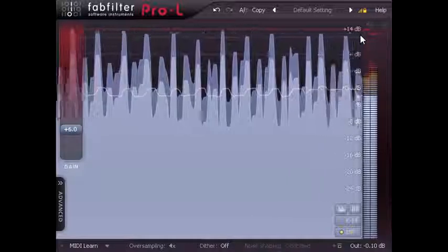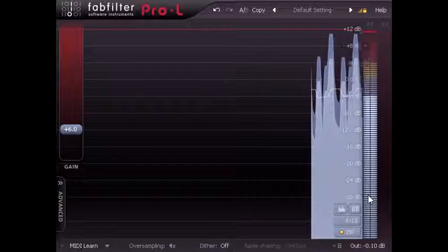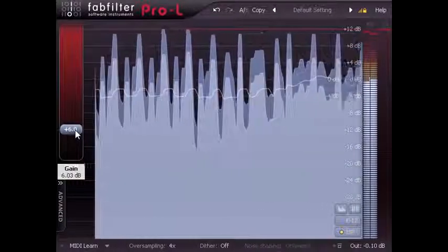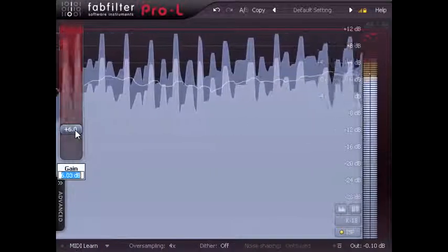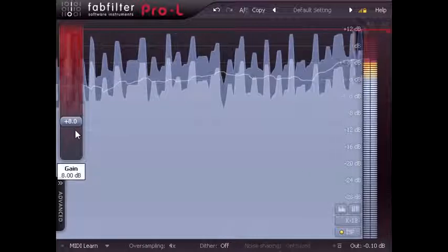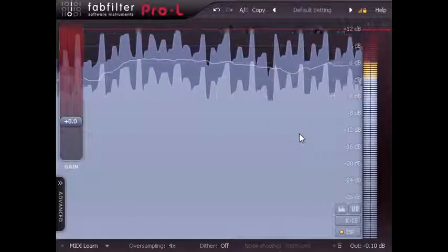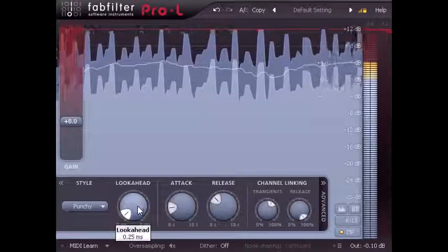The final K12 setting is the loudest of the 3 in absolute terms, with only 12 dB of headroom above our unity reference level, and this meter is designed for material intended for broadcast. The extra 2 dB of gain required to reach K12 levels will translate to 2 dB of extra gain reduction for the peaks, so you may need to take a little more care over your limiting settings.